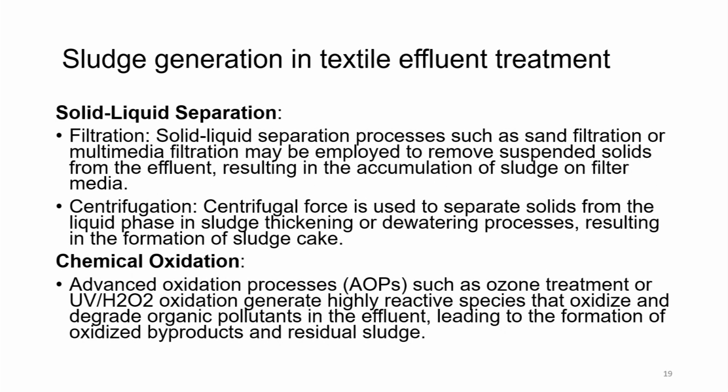So, solid liquid separation becomes very important, because sludge has to be made such that it can be transported. Filtration. Solid liquid separation processes such as sand filtration or multimedia filtration may be employed to remove suspended solids from the effluent, resulting in the accumulation of sludge on filter media.